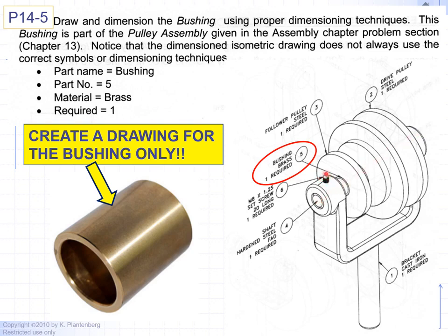You turn the set screw, which is just a screw without a head, so you can lock the shaft in place. Another option to protect this hole, or if it ever gets worn out, is to drill a larger hole and come in with this press fit bushing, which can always be replaced later if the hole ever gets worn out. You just tap the bushing out and place a new one.